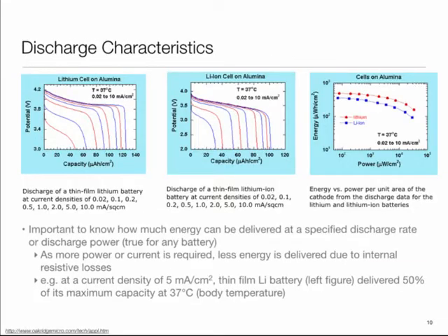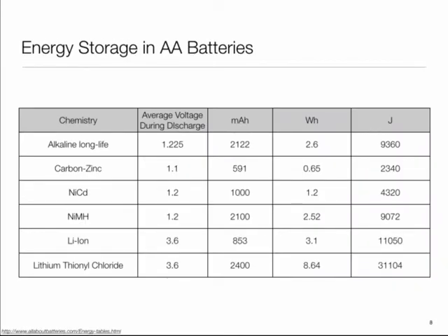Somewhere I had these numbers, like this one. An alkaline long life battery is basically saying that it is 2122 milliamp hour. So we divide it by 20, and that will tell me what current we are looking at. So this one can give me 20 hours of lifetime when operating at 106 milliamp. That's the interpretation one has to attach to this.